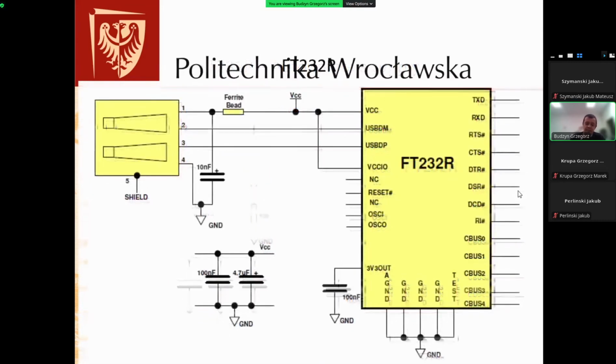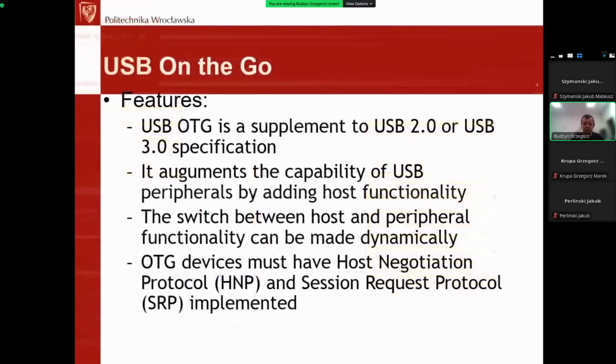So from a practical point of view, this version is really not advisable as the power supply. You don't need to use the VCC for any other chip. You can supply the other part of the PCB from your own power supply, an autonomous voltage supply. But this interface chip should be supplied directly from the USB 5 volts. That's how it should be done.